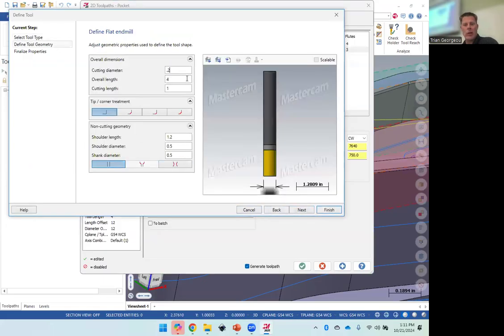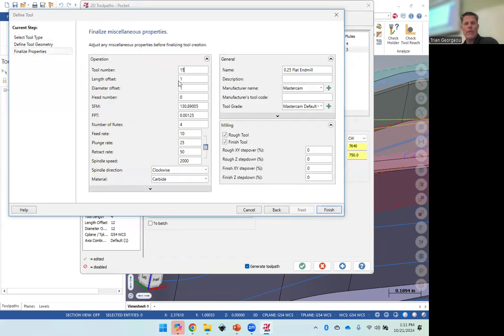It's going to be 1/4 inch in diameter. It's going to be tool number 15. It's going to be a 3 flute. Now watch this. It's such a small diameter, like a 650 surface speed will be like almost 10,000 RPM. You see that? So we're going to run 650 surface speed at a 2 thou chip load. So 60 inches a minute. We'll 30 plunge.